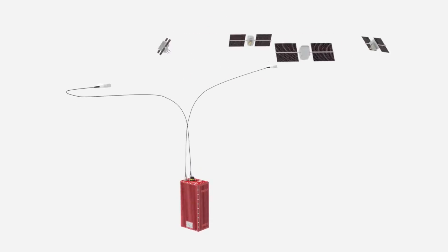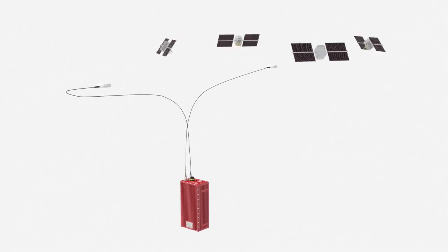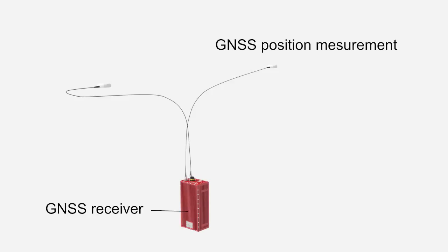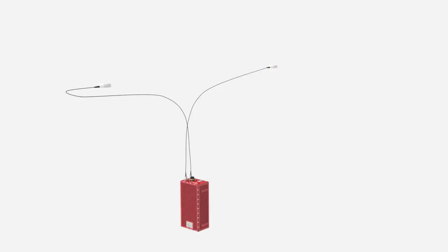The next step in the process is to tell the product where it is in relation to the primary antenna. We need to do this because although the GNSS receiver is housed inside the product, the position measurement the receiver generates is centered on the antenna itself. However, the measurements from the INS are centered on the measurement origin, even if they're later displaced. So the system isn't interested where the antennas are, it only cares where it is. By telling the product where the primary antenna is in relation to itself, it can translate the GNSS measurements to its own location, providing all the information it needs.